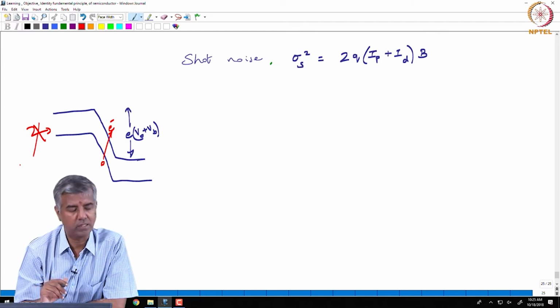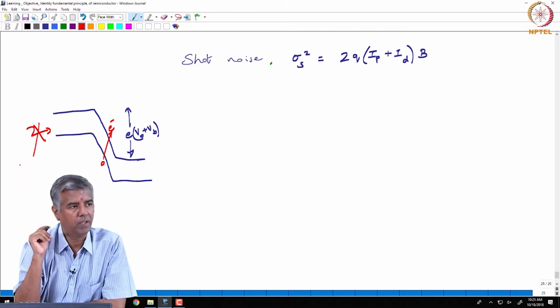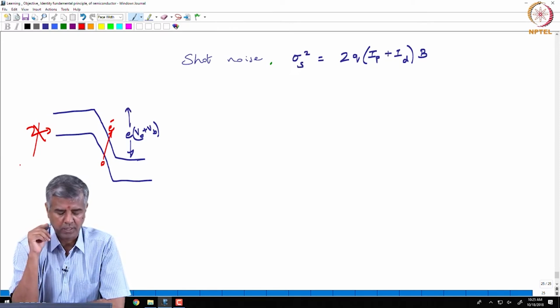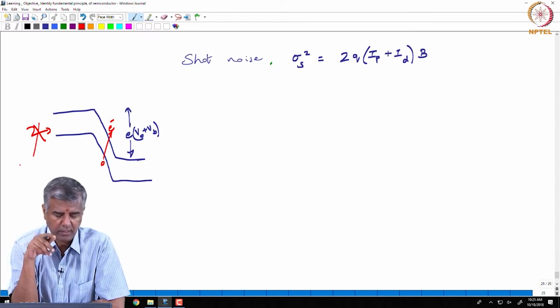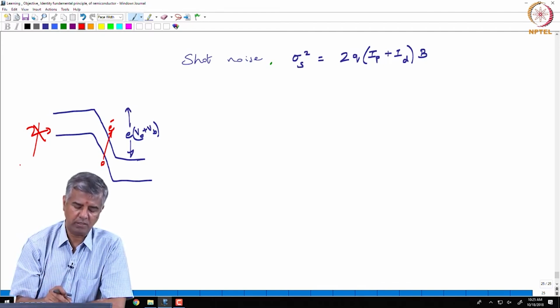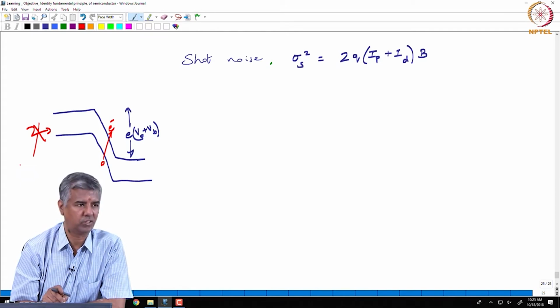There is no photon incident on the photodiode, but nevertheless you have thermally excited carriers which jump the band gap, and they become like a free electron. That process depends on the barrier height, because with larger and larger barrier height, with a little bit of vibrational energy, some phonon energy, that electron from the valence band can tunnel across and get to the conduction band.